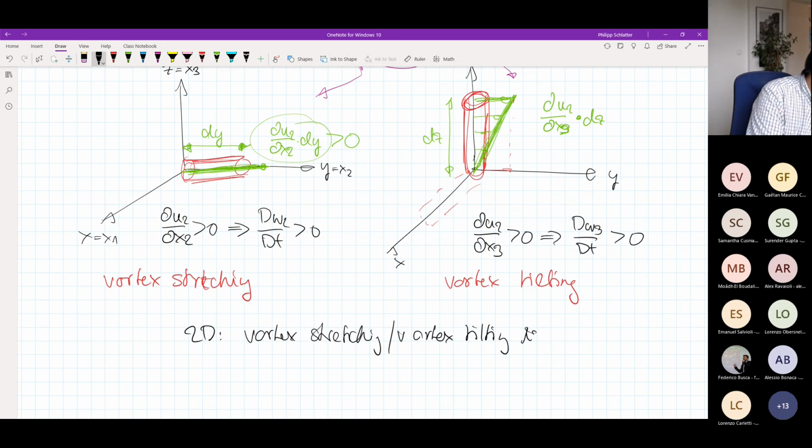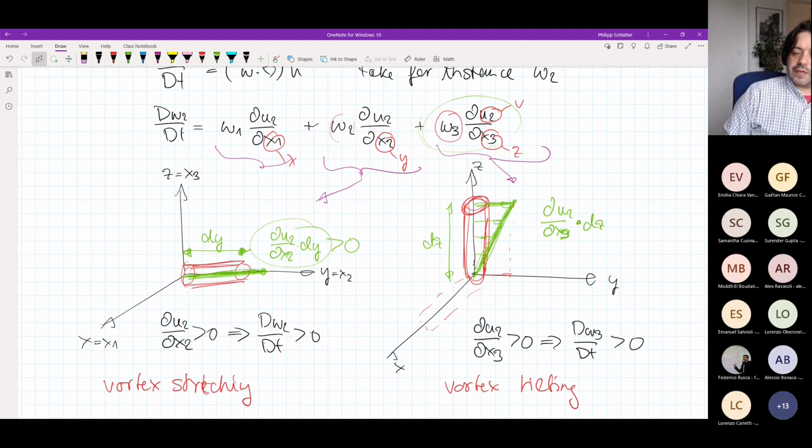And why did I say that Ramis will talk about that? Well, vortex stretching and tilting is, of course, an integral part of turbulence or a turbulent flow, where we say that one of the main characteristics is that the turbulence is vortical. In 2D, this is not really possible. So it is questionable whether you would like to call that a turbulent flow. Okay, so this here is an explanation of this additional term that we have, which replaces, in some sense, the presence of the pressure in the vorticity transport equation.